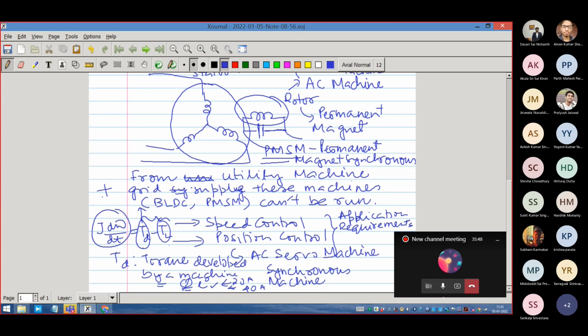Which means that the speed will go up and up till it reaches the speed of, what did I say, 500 rpm. So it has reached that speed, and at that moment it is still trying to give more torque. But then it tries to overshoot. The moment it overshoots, your control system will say no, you have overshot the desired speed limit.